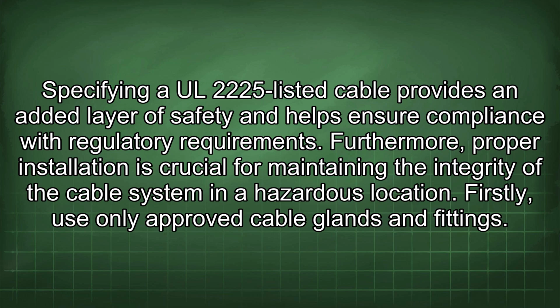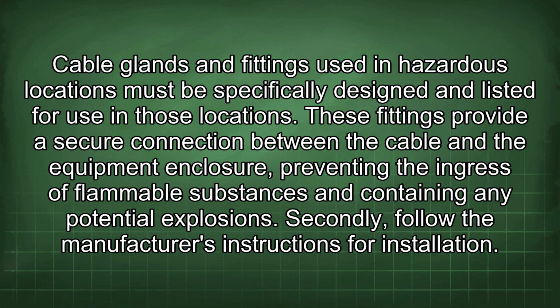Firstly, use only approved cable glands and fittings. Cable glands and fittings used in hazardous locations must be specifically designed and listed for use in those locations. These fittings provide a secure connection between the cable and the equipment enclosure, preventing the ingress of flammable substances and containing any potential explosions.